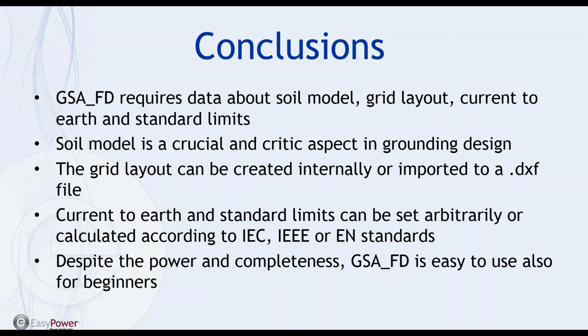The grid layout can be created by using the internal CAD or by importing from a DXF file created by other CAD tools. The debug algorithm implemented in GSA FD helps the user to rectify the data, for example overlapping lines, doubtful connections, and so on.